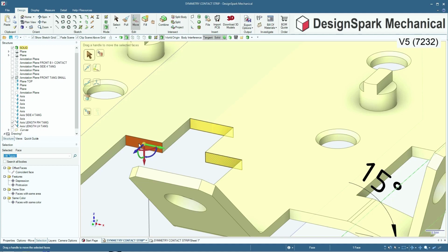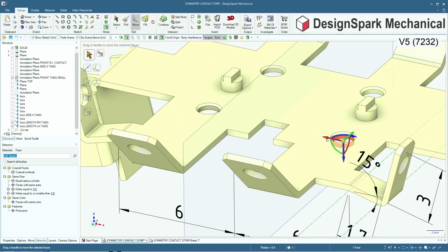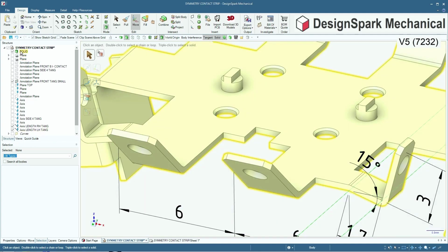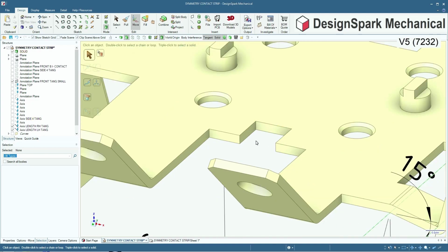So it's remembering its group in any clicked member of the group and at any time, because I can go back here, I can move this face, which has a mirror linking, as you can see, and I can now go back here and it will come. Sorry, so I've moved one, but I can also now move the three, which is very handy. There's no structure browser marking or symbols to record these informal face selections, and remarkably, these remembered groups are still available upon file reopening.